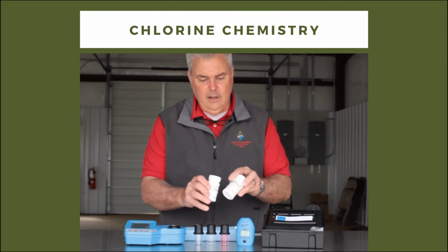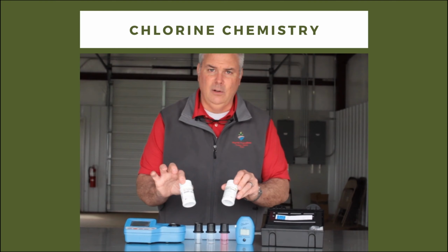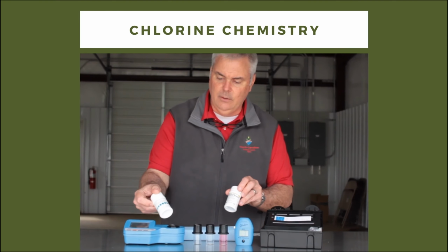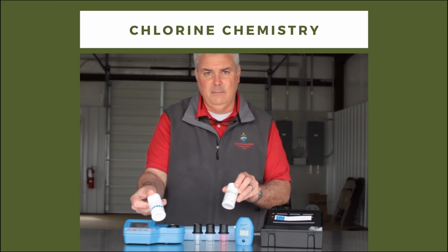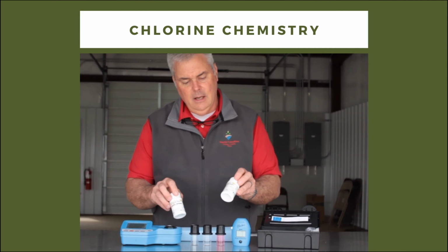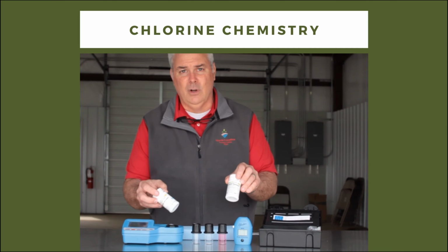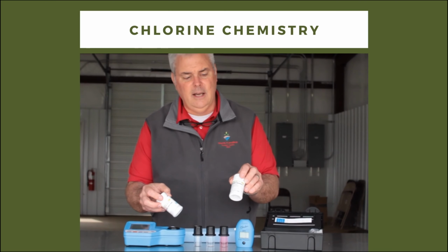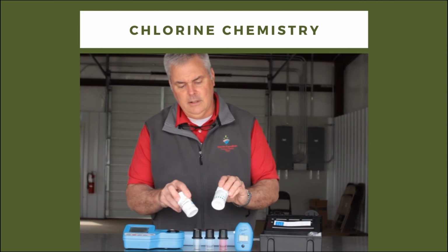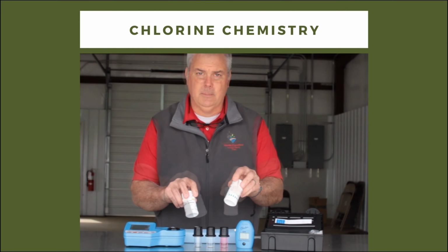Here we have two different test kits. One of these is for ultra-high chlorine concentrations, and you can see that the range for that is from 0 up to about 750 milligrams per liter or parts per million. Most growers would be interested in using much lower concentrations of chlorine than that, and so this would be more appropriate. These test strips measure from 0 up to about 25 milligrams per liter.